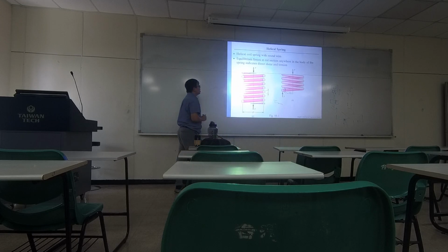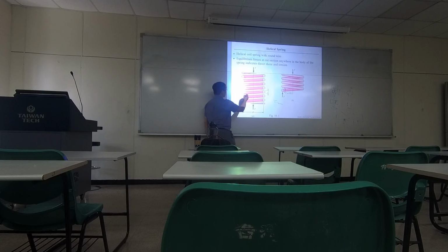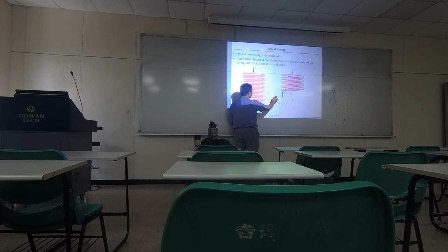Okay? And let's say you are trying to compress the spring, and you still pay attention to somewhere inside the spring material. That pushing force is going to shear everywhere inside the spring, and it's going to be a shearing force up and down along this cross section. So there's also shearing stress.